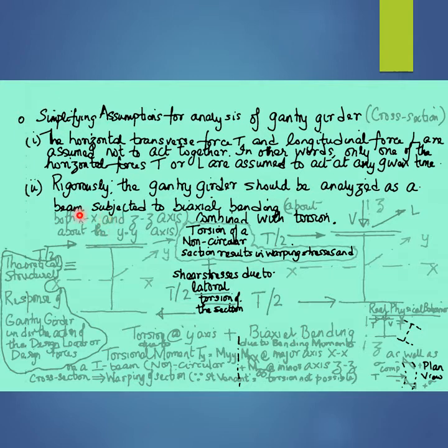It is intuitive that the anti-symmetrical components of the horizontal transverse dynamic force T obtained from the decomposition of the transverse force T into antisymmetrical and symmetrical components results in torsion of the non-circular girder cross section.